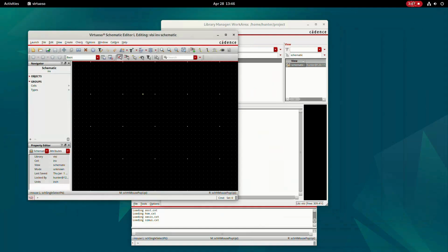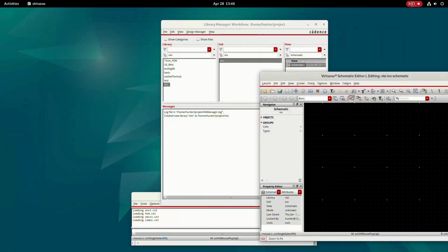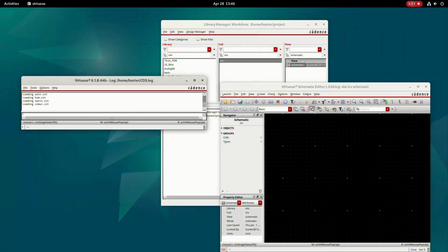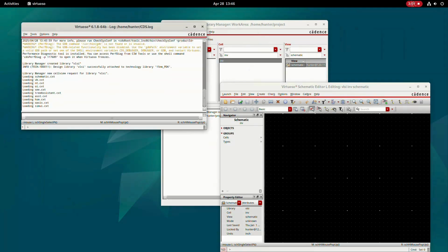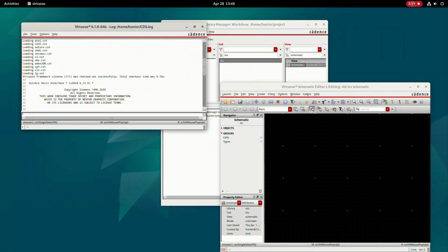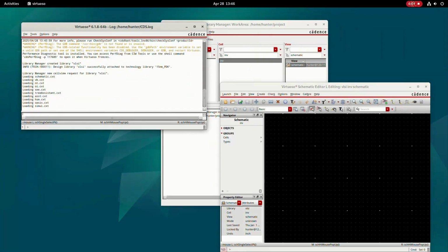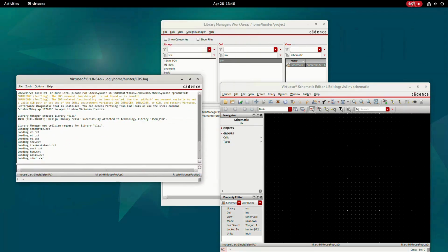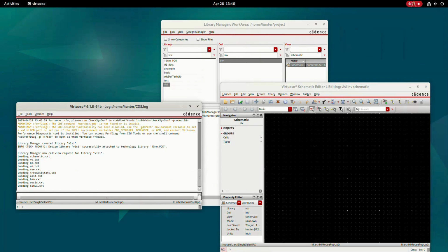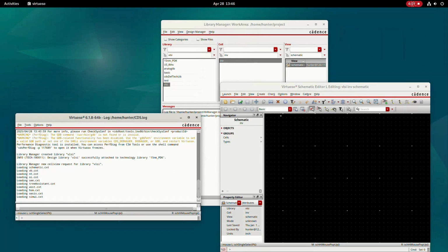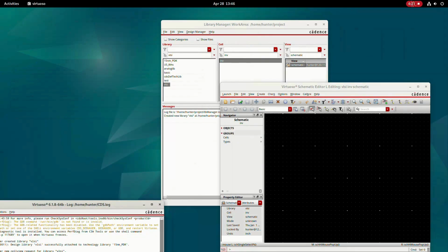Then you can see a window like this. This is an editing window for a schematic. I need to say another thing. This is called the CIW window of Cadence. You can see everything here. If any error occurs or any information or warning, everything will be shown in this area. It stands for Command Interpreter Window. You can use this to verify you are doing things correctly or whether any warning is arising. Now there is no need to check. I will say when you need to check it.